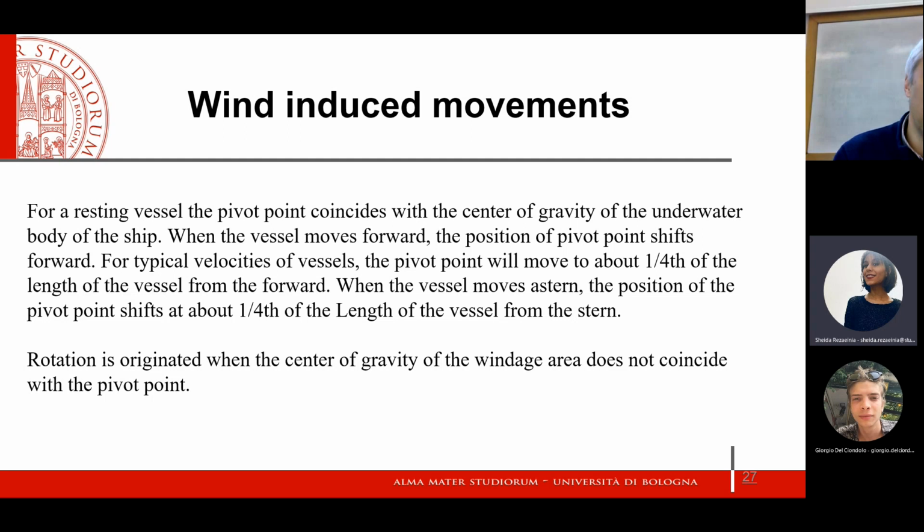Because I plan to make an exercise of computation later on. I think the best way to understand how to compute the mooring forces, the rotational moment, which will depend on the eccentricity that we just introduced, and the longitudinal and transversal components, is to refer to an exercise.